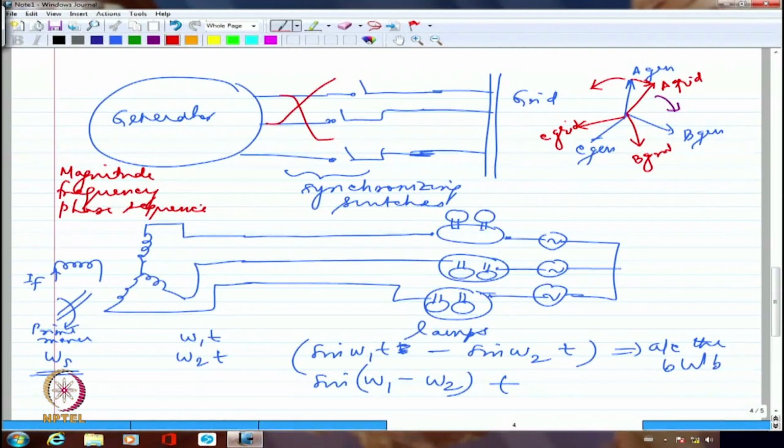But you can't do this interchanging when the generator is live. So you have to switch off everything and start afresh. You can't do this when the generator is live. Never do it when it is live. So what you will do is switch off the whole thing, start from scratch, start the DC motor again, bring it to 1500 RPM, bring the excitation to the rated value, then look at the magnitude and match the magnitude, right? Now you know the phase sequence is matching at least, so you don't have to worry. Then match the frequency by looking at the rate at which this is changing.